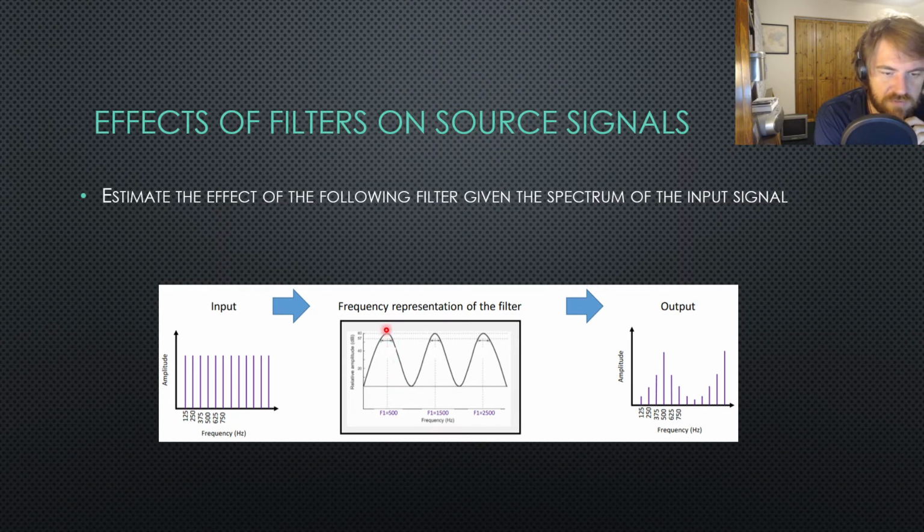The center frequency here is 500 hertz. And we see that we've got 500 hertz here. So this is going to pass completely. That's why over here, 500 hertz is just as tall as it was over on the left. 500 hertz passes completely. But you can also see that it doesn't just cut all the way down immediately like my filter did. Mine was like a square, like that. So frequencies either completely passed or they were gone entirely.